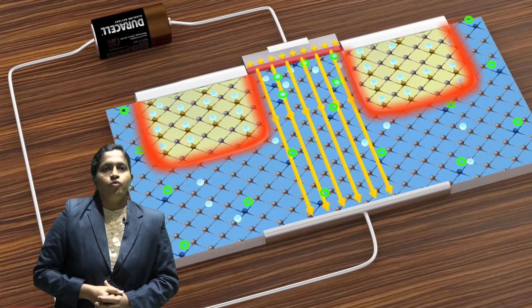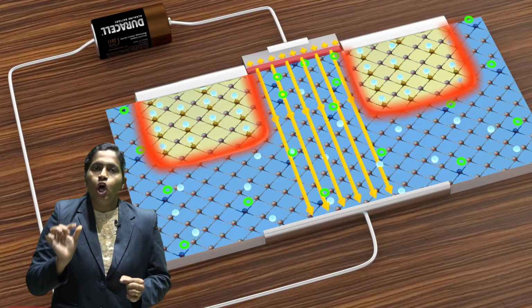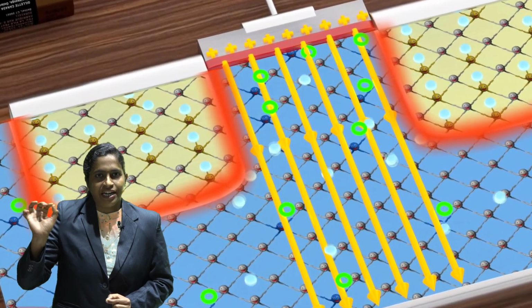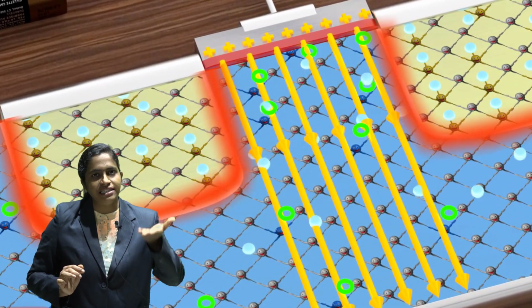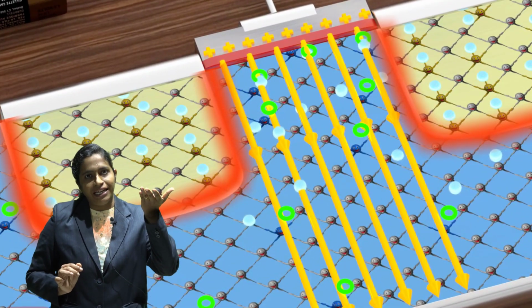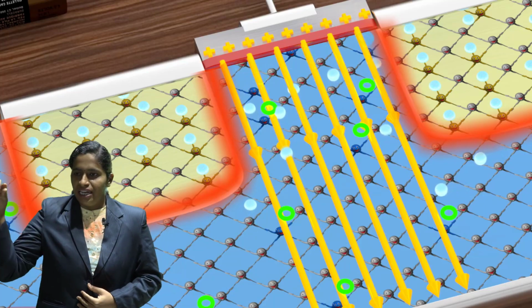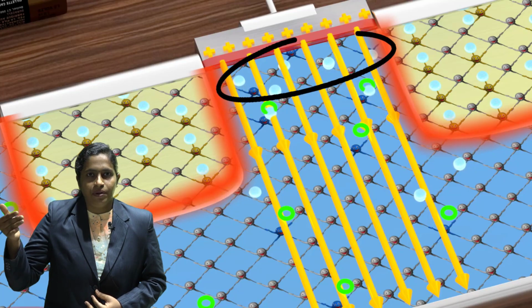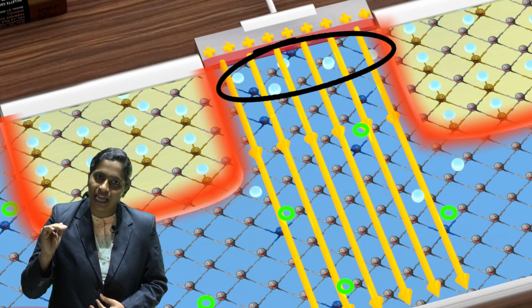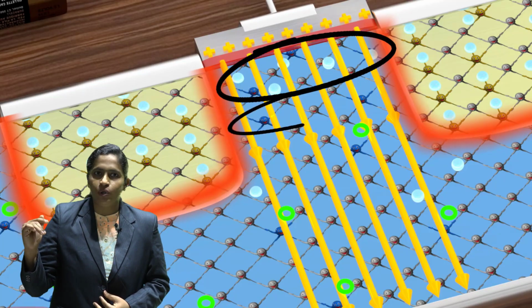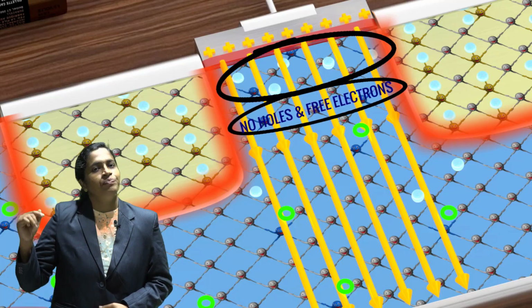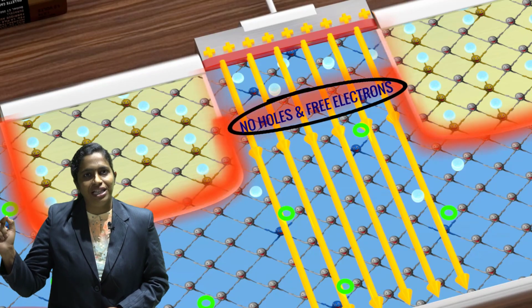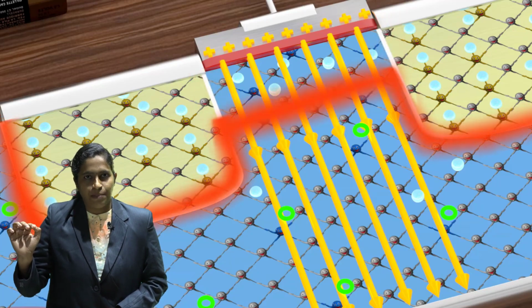Initially, when we apply a low gate to source voltage, some electrons are attracted near the surface. When we increase the gate to source voltage, the layer between the two n wells becomes n type. Initially it becomes less p type, and when we increase VGS, it becomes n type, and the channel is formed between the two n wells in an n-channel enhancement type MOSFET.